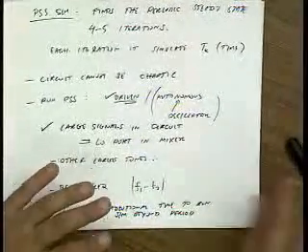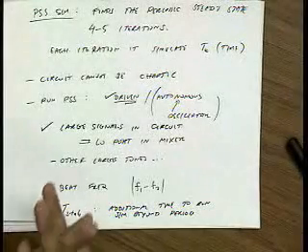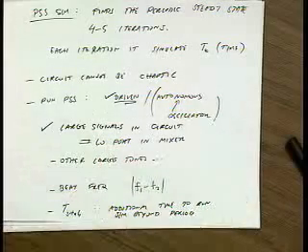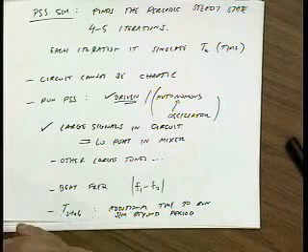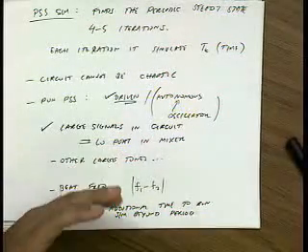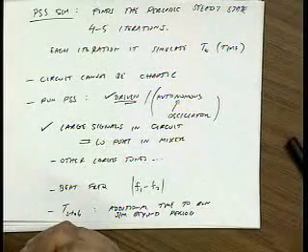So let me just repeat. We haven't said anything about mixers. All we've said is periodic steady state analysis tries to find the steady state periodic solution. Okay? And if you think about normal SPICE, there's no way to do that unless you simulate it for a long time. Now some circuits get to periodic steady state very quickly, okay?